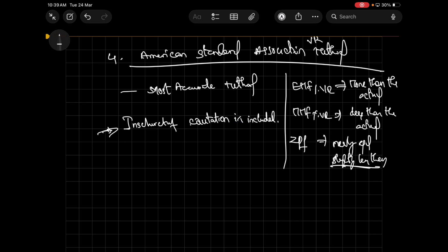So in order to get the actual testing, what we are supposed to do is apply the full load, and also apply the no load, get the no load and full load values and find out the percentage regulation. That is the normal testing method. But instead of wasting a huge amount of power, I am going with these methods. So that we can estimate for a large rating machine the percentage voltage regulation to assess the machine performance correctly here.